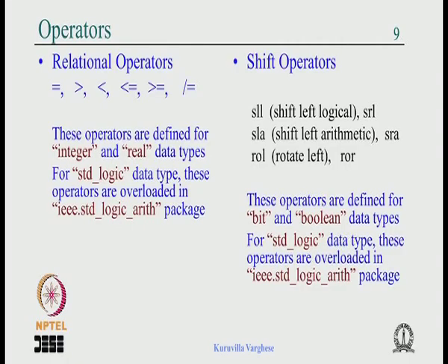And once again, shift left arithmetic, shift left logical and the others are all defined for the bit and boolean data types. For the standard logic data type, they are overloaded in the std_logic_arith package.